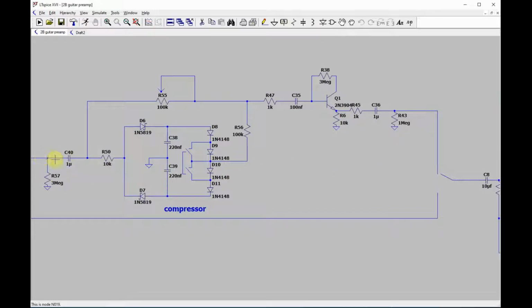Okay, here's the compressor. You've got signal coming through here, and the output impedance is like 100K, I would say. Yeah, because this is going to ground basically, so it's 100K, or if anything else is in parallel with it, it drops a little bit more. So you can plan on 100K as being safe. So you need to go into a meg. This output impedance is 100K. Input impedance here is going to be like 1 meg or more. So that is a step going up by a power of 10.